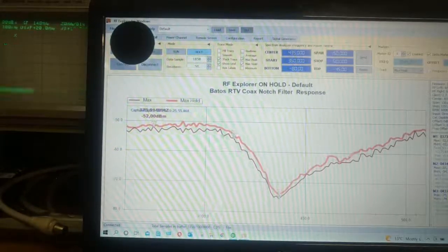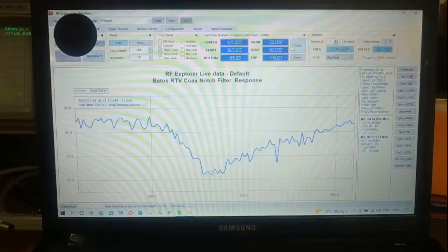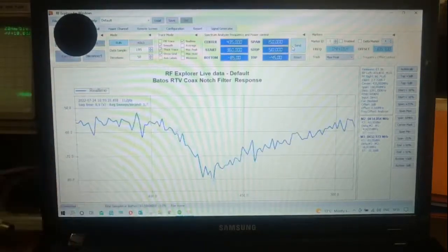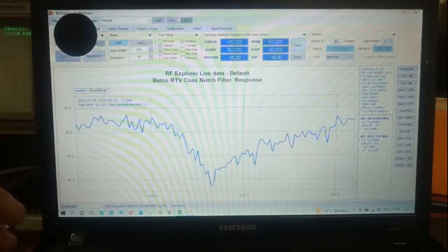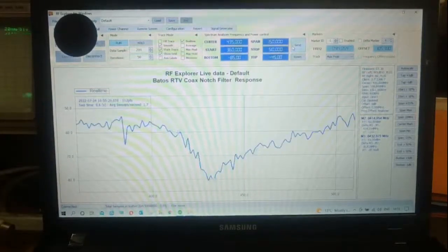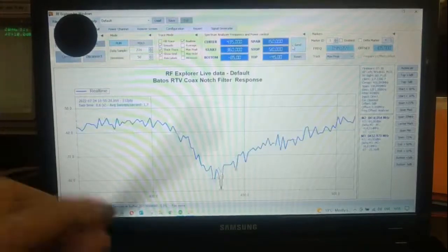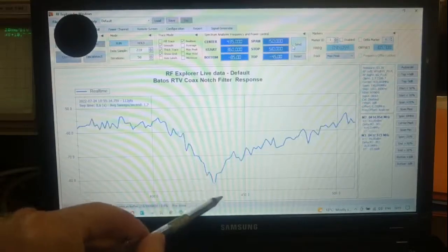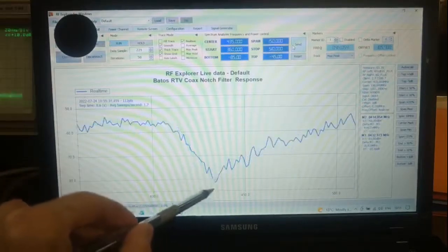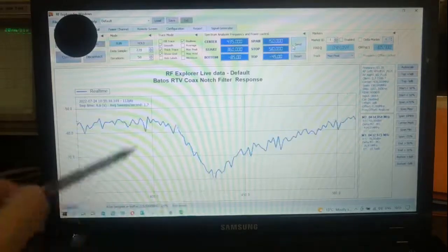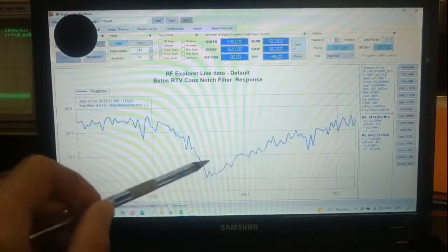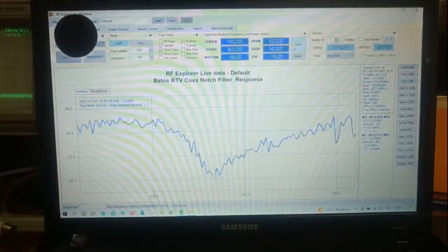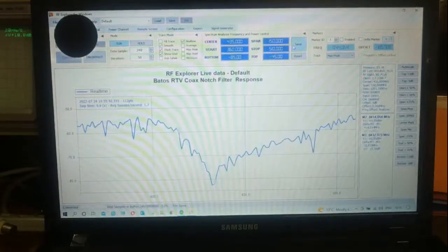Now, of course, with any filter, whether it's a notch or bandpass or a stop filter, etc., or for that matter, any inductive device, it has not only just one resonant frequency, although it's made specifically for that frequency and it's the greatest attenuation there. Most of the devices, as I mentioned, would have multiple different resonances. At third harmonics, they call it, at their odd harmonics, they will have attenuation.